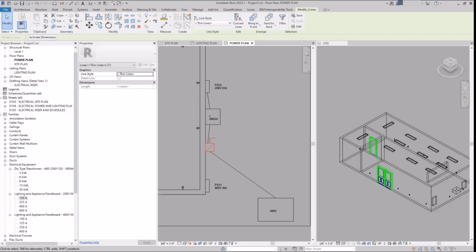Service entrance disconnect is what it's called. And you call it that because the service is the 480 transformer. Yes. The point of service. I'm sorry, we'll just keep it simple. The service is from the 480 volt utility transformer. Gotcha. Like what is it called? Primaries on the other side of that 480 transformer.